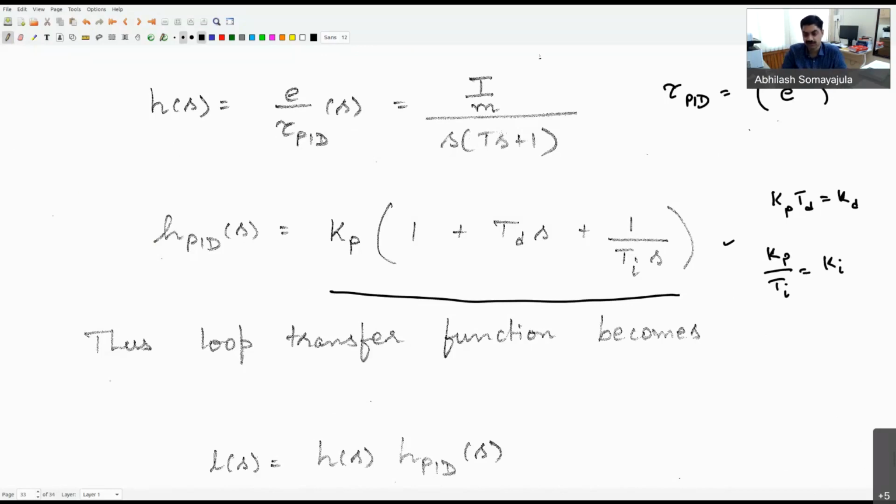A typical PID controller. So what is happening, I'm trying to understand this so-called loop of the system. Is it stable or not is what I want to figure out. So given some error, the PID will generate some torque, some moment, and given that moment will result in some error. It's a closed loop system. It keeps going on continuously. But I want to break that loop at some point and observe. If I give an input amplitude of 1, what I get back, is it greater than 1 or less than 1? That will tell me whether the system is amplifying my errors or decaying my errors.